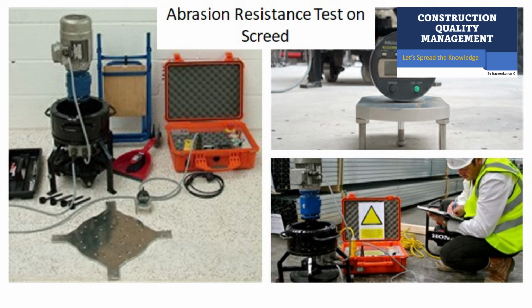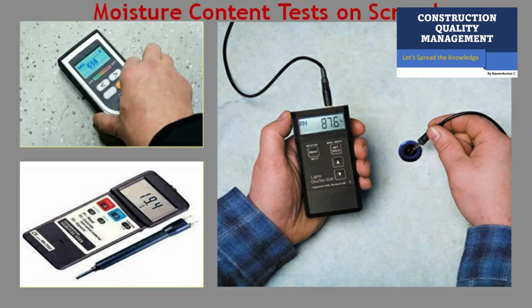Once these are done, the last test on the screed, which is non-destructive in nature, is moisture content or any kind of dust check. For the dust check, you can use a broom and just wipe it to check whether any dust formation or surface powder formation is there or not. The moisture content can be checked using these devices you can see on your screen.